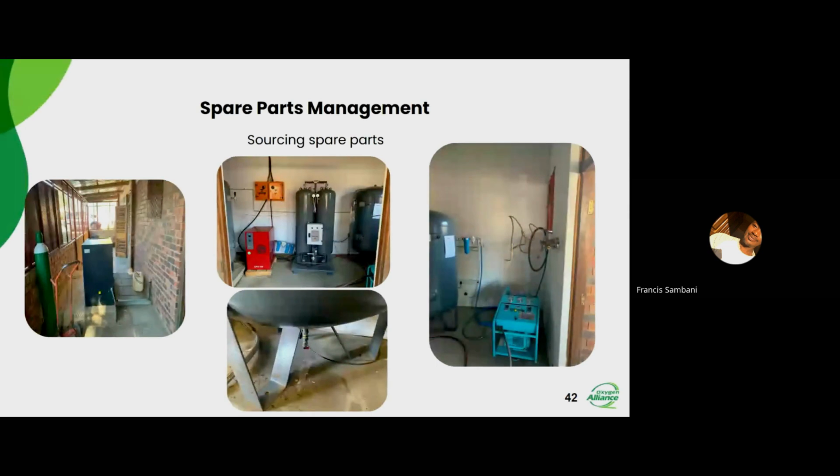It wasn't what I'm accustomed to. So they had the air compressor, and then after the air compressor they had the air storage tank, and then after the air storage tank they had the dryer, and then the filtration, and then the PSA generator, and then the oxygen storage tank, and then the booster compressor, which you can see on the far right. And if you can also see on the bottom middle picture, you have the vessels. Both of them actually were not boarded down, so that's also a hazard on its own.